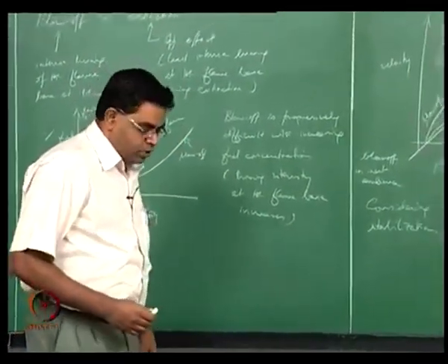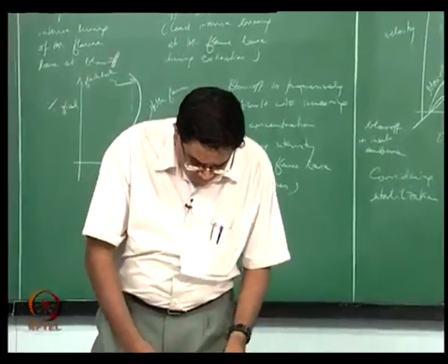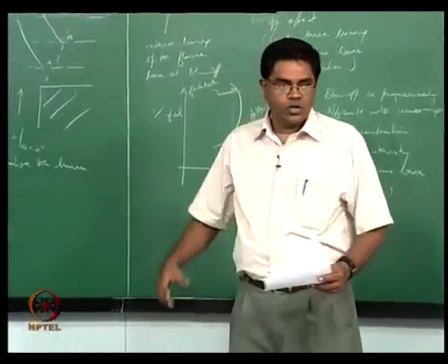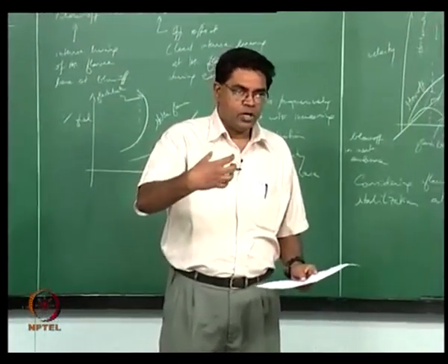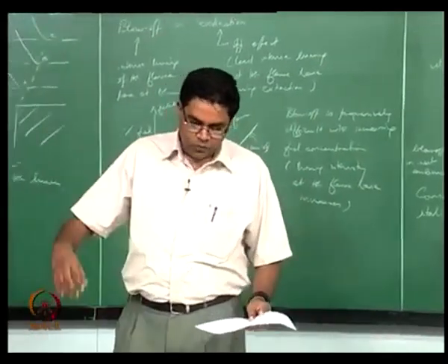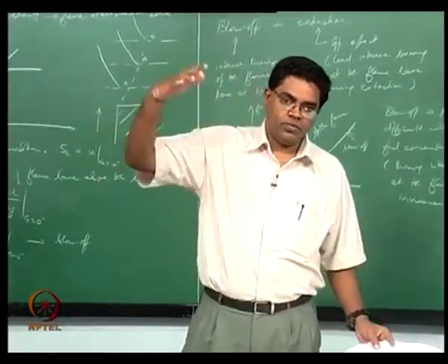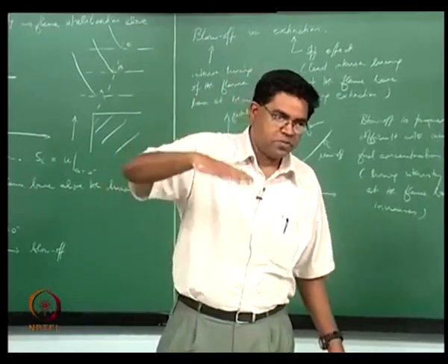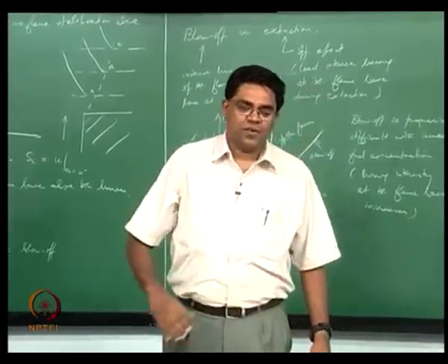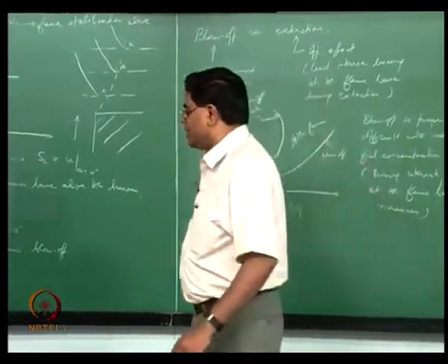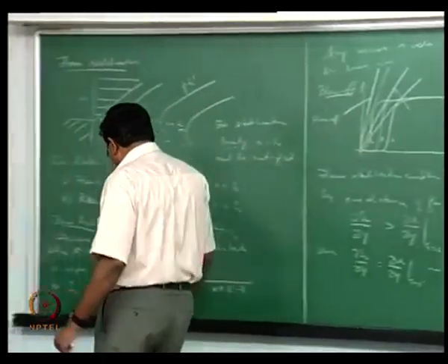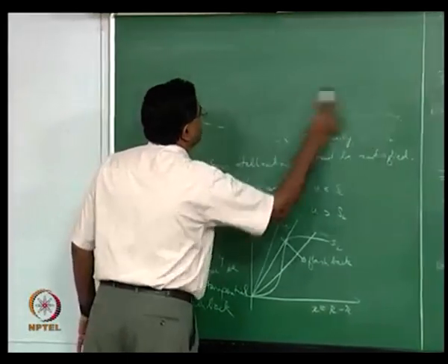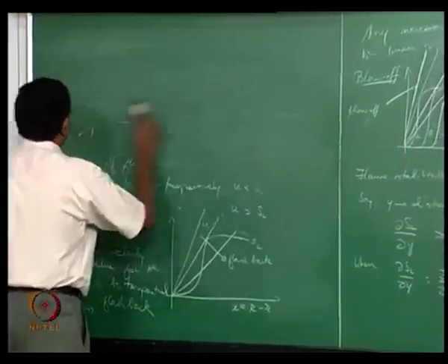The other thing that I would like to point out is what we have been primarily talking about is flame stabilization over a burner rim, right? But in general we could be talking about flame propagation in a duct. So for example, when you now think about a flashback, we'll say okay fine, let it flash back and see what happens, right? So how does the flame propagate further down into the duct? There are some things that I would like to just say about flame propagation through the duct before we get to the next step.